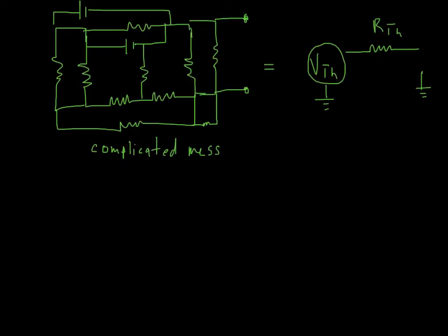This is where all of the theory on source impedance and output impedance is going to pay off. So if you look, this is just another version of our circuit we had. Now I'm calling it TH for Thevenin. So basically, any complicated mess has a Thevenin equivalent. Let's write that down. Thevenin equivalent. And then the graphical method that we had just on the other slide is the way to find the Thevenin equivalent. So in real life, if you wanted to find the Thevenin equivalent of the circuit, you could rewrite it to actually just model it like this.